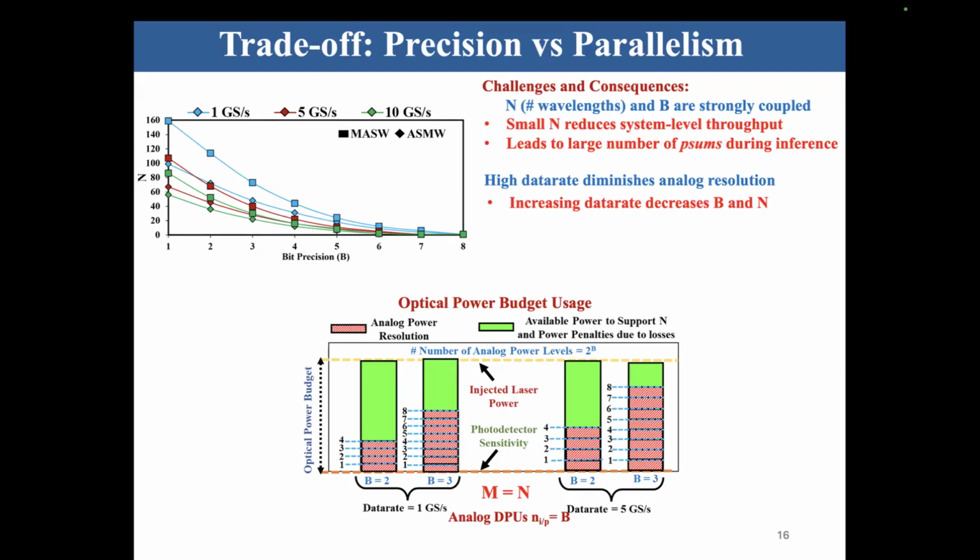If the processing is not limited by the kernel size itself, because in some algorithms the kernel size is small, then with a large tensor core you will have some devices going idle. We have done that kind of work as well. So it has to be balanced, but the general approach is to have as large a parallelism as possible, and then reroute the signals if the kernel size is small, to achieve a high hardware utilization rate.